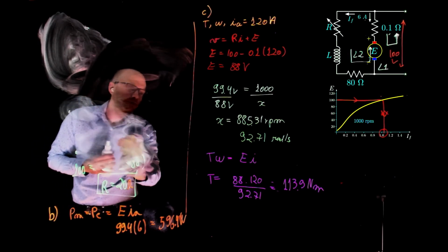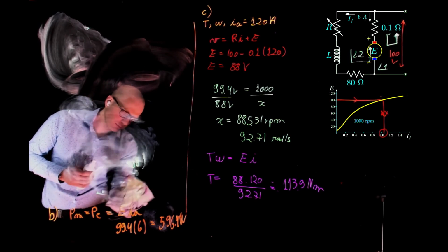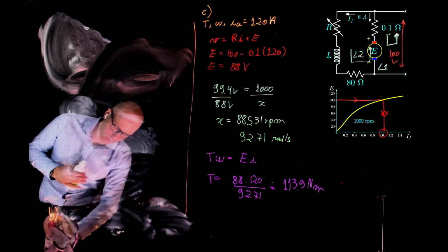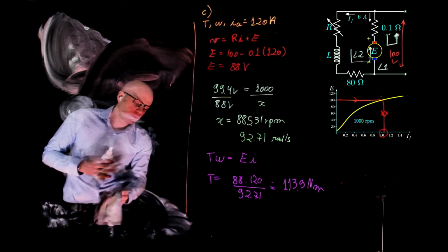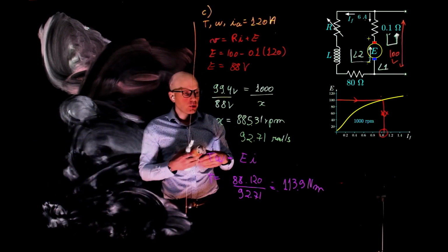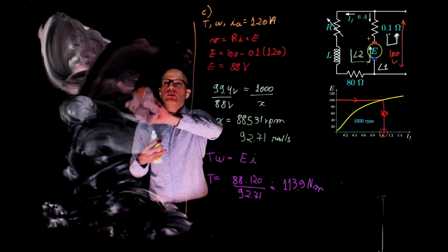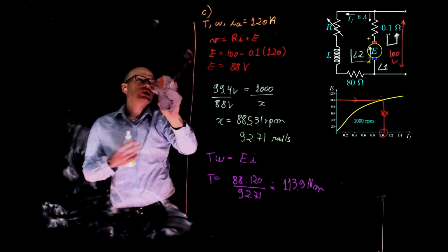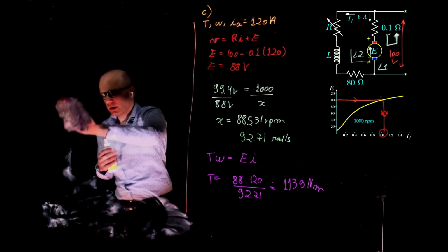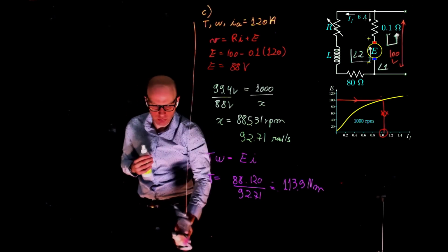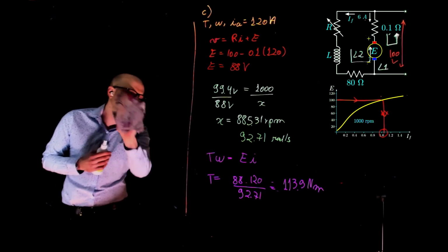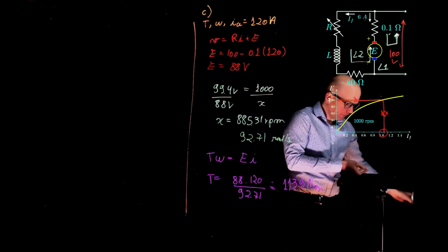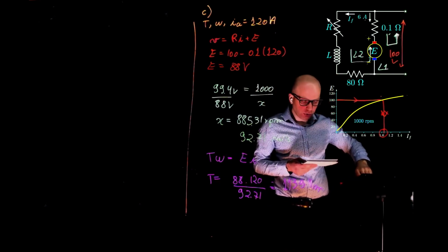So I'll let you think about how to calculate the stall torque. In the meantime, how would you guys calculate it? What is the first thing we need to calculate the stall torque? Is it V over R? V over R, exactly. In other words, I think what you want to say is the current at zero speed, which is indeed V over R, because at no speed there is no back EMF, E is zero. If E is zero, the only thing opposing current through that inner loop is the resistance. What else do we need to calculate the stall torque?